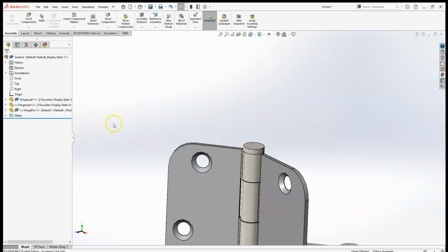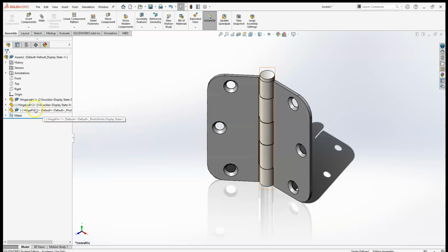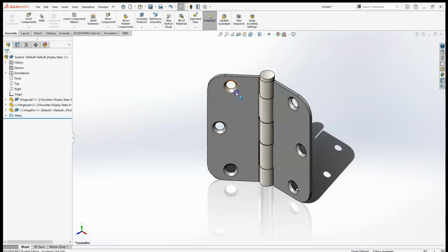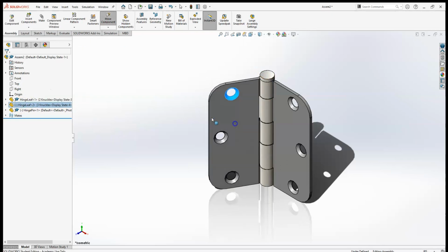So that's looking good, but you'll notice I've actually got 2 degrees of freedom showing up here, right? Or at least 2 parts that have at least 1 degree of freedom showing. It actually is 2 degrees of freedom total here, just because this thing has a rotational degree of freedom and that has a rotational degree of freedom. This one's easy to see, right? You can kind of see the flat moving.